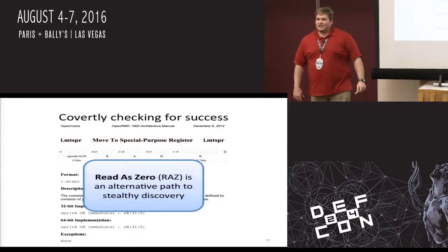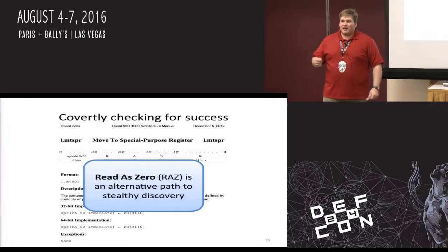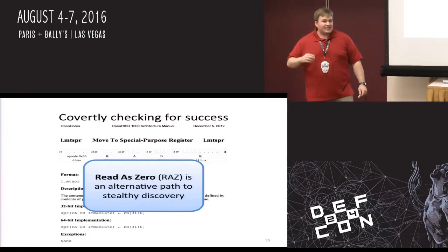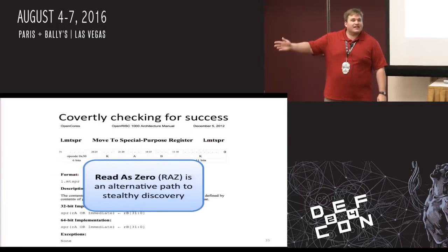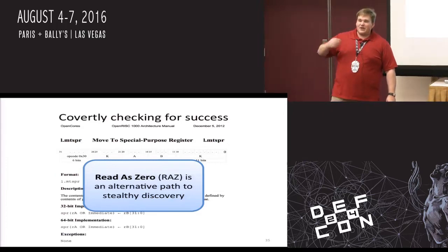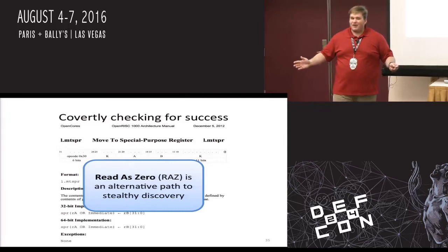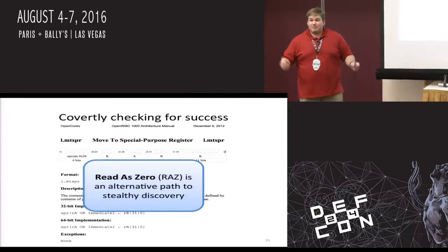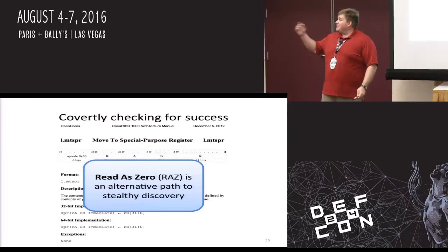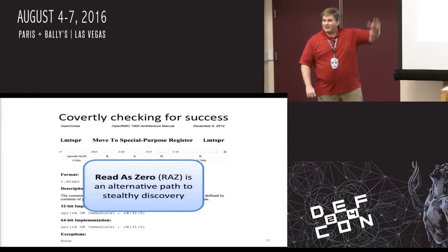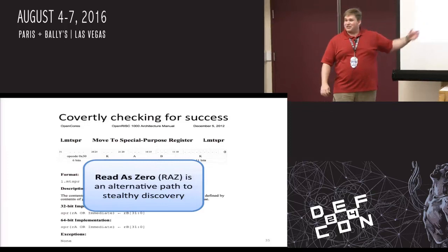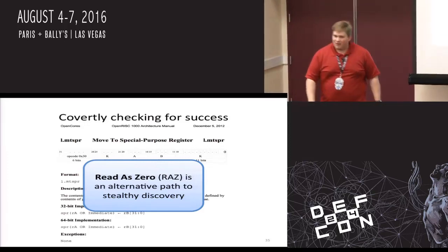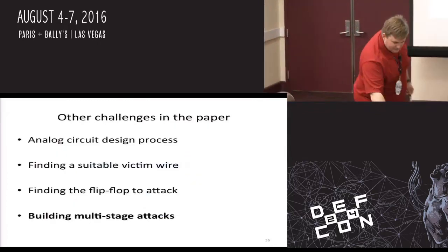Processor designers say, hey, it's actually more efficient for us just to return a 0 value if you try to read something you shouldn't be reading, as opposed to giving you the actual value or giving you an exception. So they have this context-sensitive behavior. When you read a register, if you don't have privilege, it's 0. If you do have privilege, maybe because of our attack, you have some non-zero value. So we'll do our attack sled, and then we'll read this register. If we get anything other than 0, we go escalate our attack to the software level. And so that's what we do.